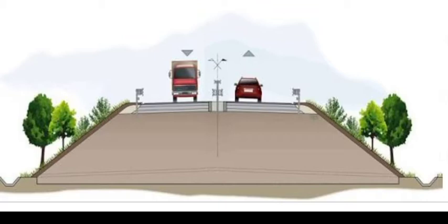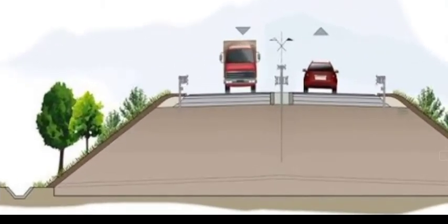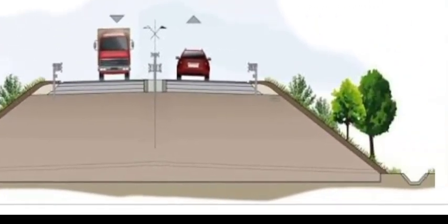So earthwork includes construction of embankment using locally available soil, excavation for road stretches in cutting and grading, and adequate compaction of the bottom surface. Excavation of earth is also done by providing longitudinal roadside drains. Here in the diagram you can see we have provided side drains on both sides, right?